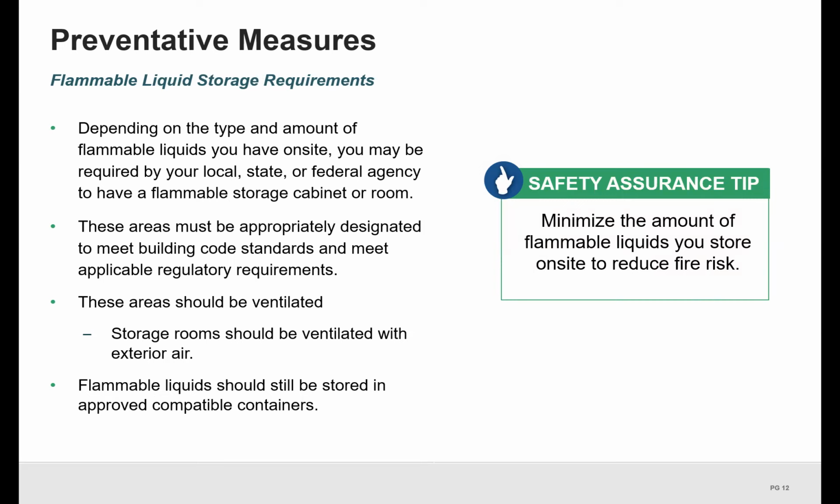over 120 gallons of flammable and combustible liquids in containers, 660 gallons of flammable and combustible liquids in a single portable tank, and 25 gallons of extremely flammable liquids with a boiling point below 100 °F, such as ethyl ether. Please note that the extremely flammable liquids must be in approved containers.